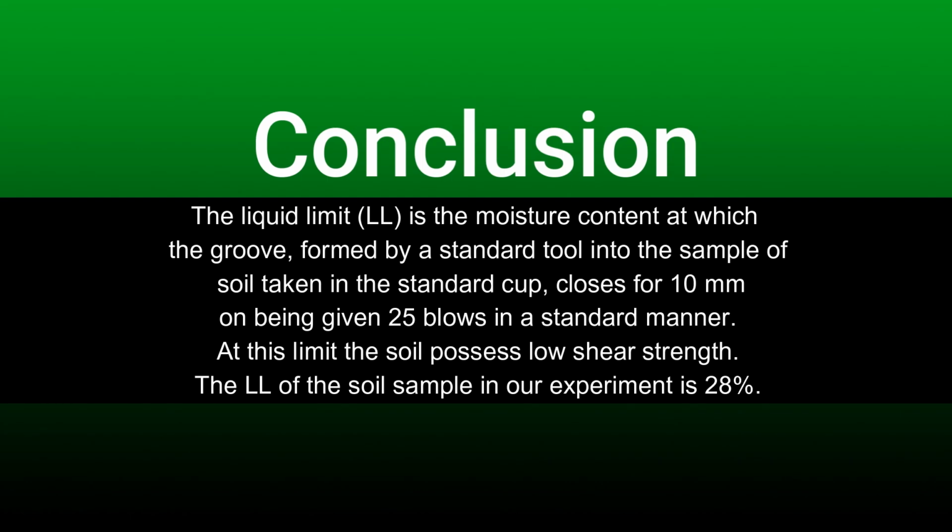In conclusion, the liquid limit or LL is the moisture content at which the groove formed by the standard tool into a sample of soil taken in a standard cup closes for 10 mm on being given 25 blows in a standard manner. At this limit, the soil possesses low shear strength. The LL of the soil sample in our experiment is 28%.